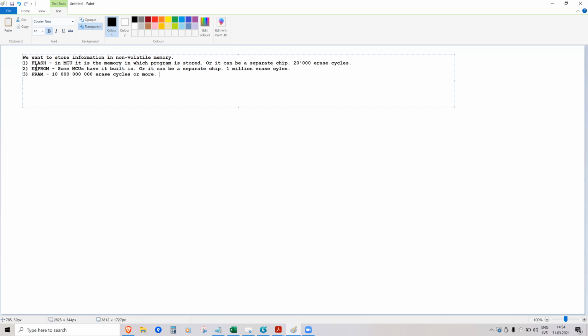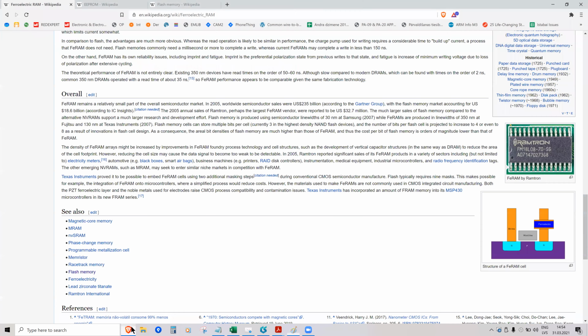So it's better to use ferroelectric RAM. In such cases, if you know that there will be many writes, just use this chip. It's like 2 or 3 euros more expensive, but it's almost indestructible. And also, there's a series of microcontrollers from Texas Instruments, which has all of its memory built as ferroelectric RAM. So you can just use the microcontroller's internal flash memory to log data.